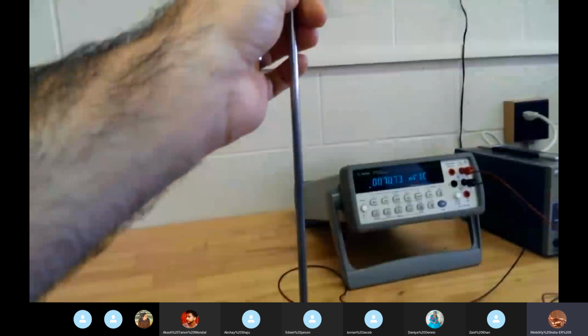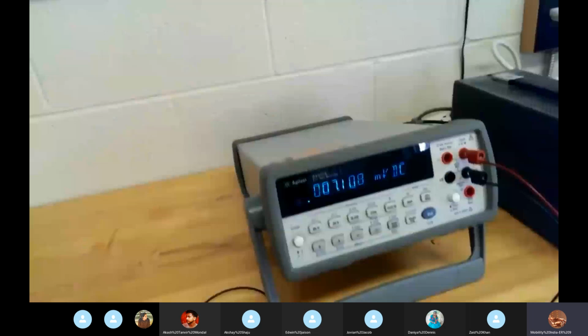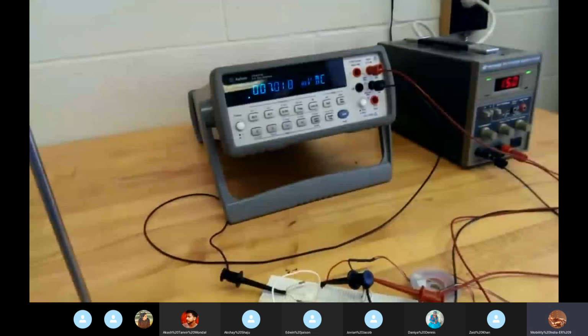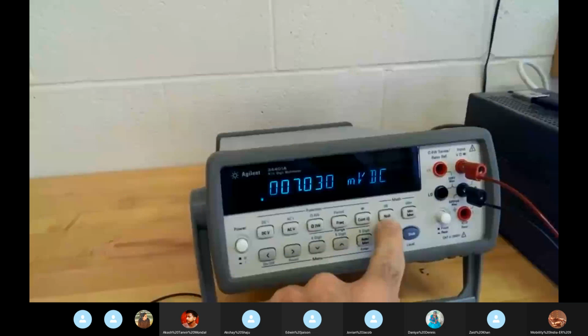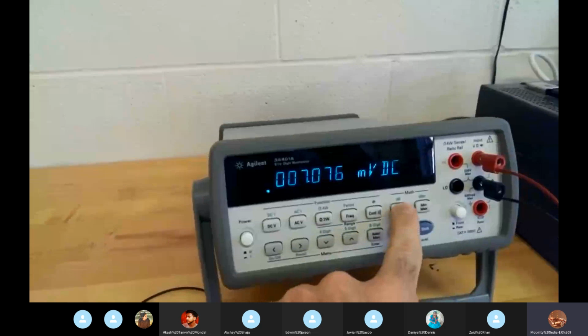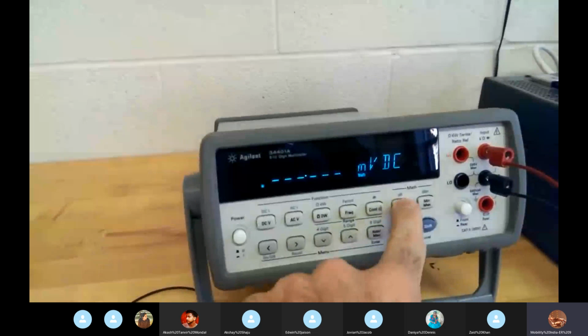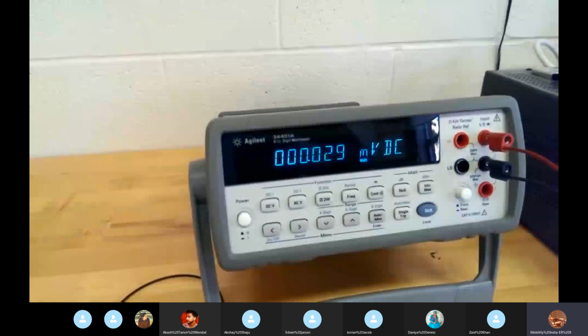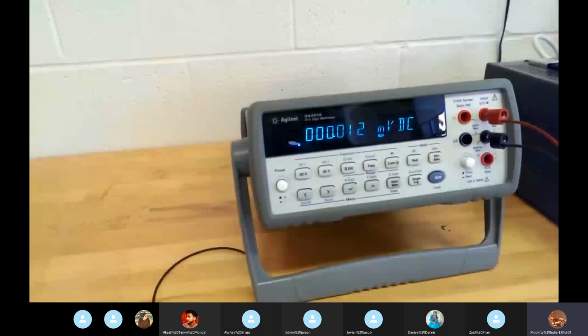So the procedure for getting your voltage readings is as follows. You'll first push null on the digital multimeter. You can tell that zeroes it out. Then take this hook to the end of the cantilever beam, making sure that it doesn't swing too much.